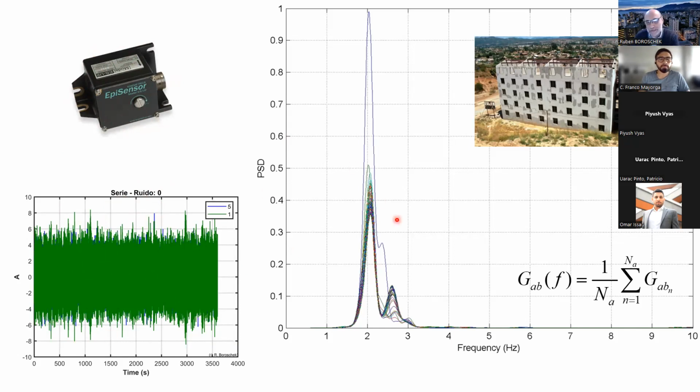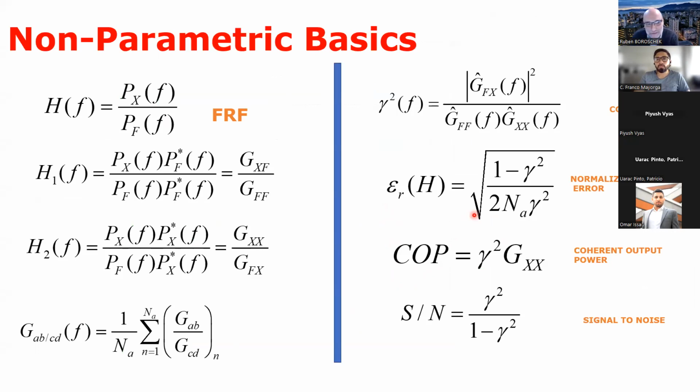So we teach how to get the maximum response, the frequency content, and also the evolution RMS value or some characteristic of the time characteristic of the signal. And if you transform it to the frequency domain, we go through standard frequency domain identification, parametric or non-parametric, just picking for the frequency. For example, this record from this building, we just grab some students, put the sensors there, and measure the response and get the first mode and second mode, torsion, mode shapes, and damping of the system using very simple techniques, non-parametric, that you can teach in undergraduate course. And these are the basic formulas. I'm not going to go through them, but they are quite simple, and I can teach them at the undergraduate course.